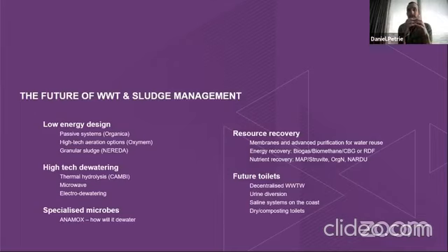Can we use targeted treatment processes in our sludge handling plant to recover as much energy as we could, either as biogas or biomethane, or even combusting those dried sludges? Can we use specific process conditions or technologies to recover targeted nutrients from that sludge, like ammonia and phosphorus? So there's a kind of interest in that, and those will shift how we use dewatering equipment and how we will structure our dewatering designs.